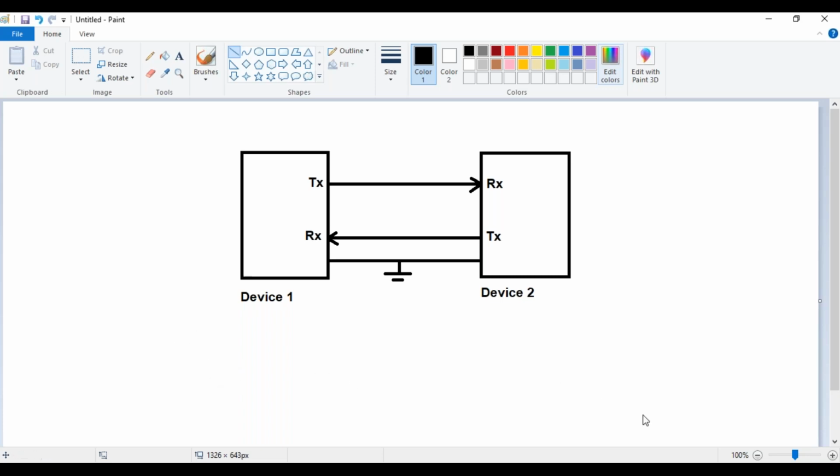Okay, individual ground also is okay. Actually, you have to provide ground in common, because we speak things with respect to the baud rate, bit rate, and all. Now, generally, when you are establishing the communication between two chips, they will be closer to each other because you have to make the hardware connection. So you have to provide the ground in common. So both of them should be provided with ground in common. Individual ground, in the sense, it is fine even if it is a very far distance, but ground should be provided for the two devices.